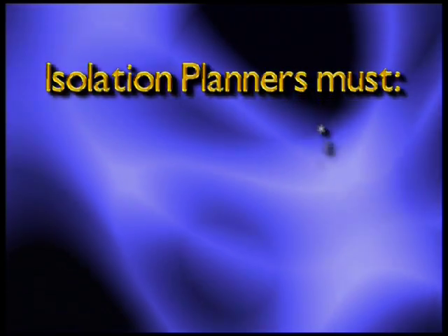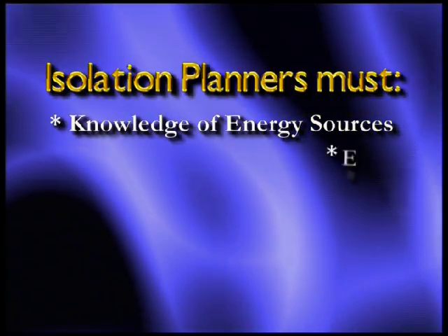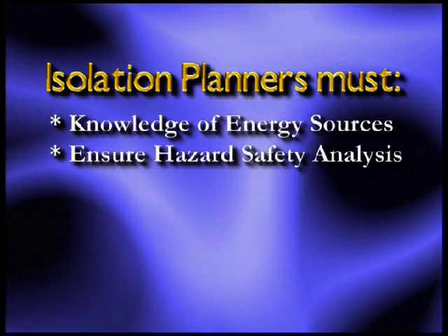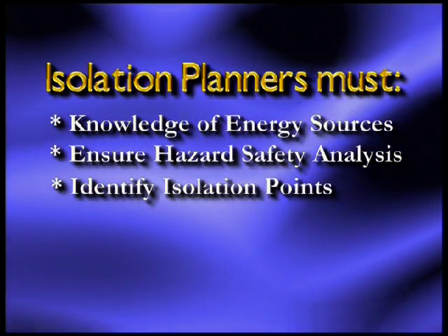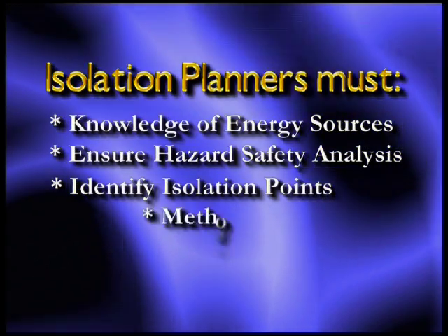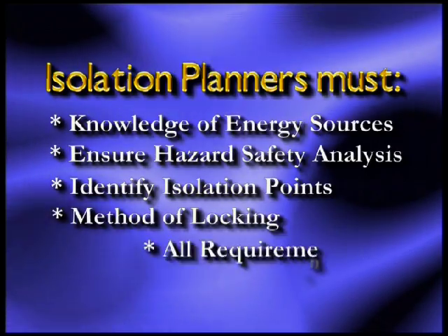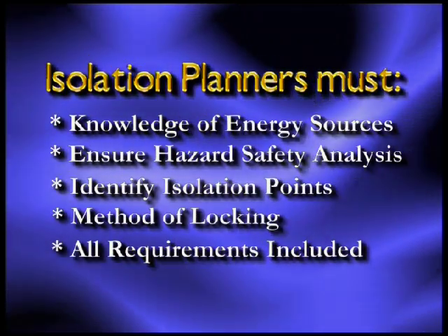Isolation planners must have knowledge of all energy sources associated with the equipment. Ensure hazard safety analysis is conducted to determine isolation requirements. Identify the relevant energy isolation points. Identify the method of locking energy isolation points. And ensure that all necessary requirements are included in the isolation permit.